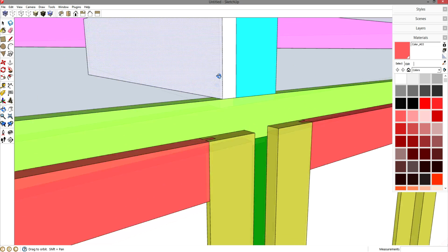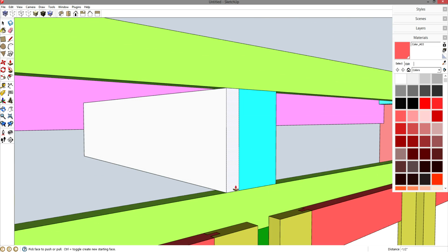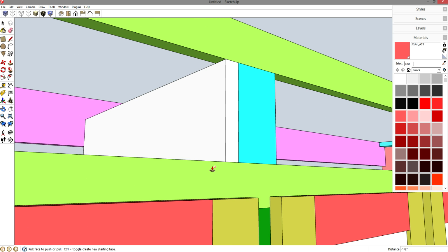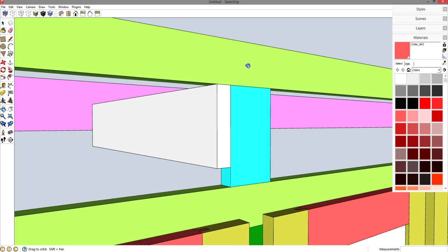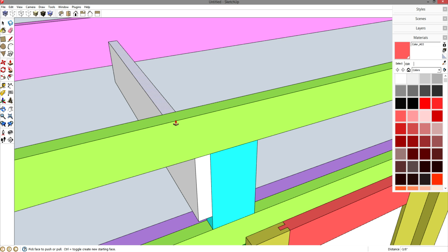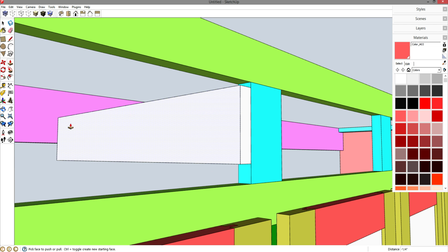Now, the drawer slide is about half of an inch off the base of here. So let's go 0.5, enter. And I also want to just put the bottom of the drawer right onto the bottom of the side. So let's push this again 0.375 because I'm going to use 3/8 of an inch plywood for the bottom of that. So that's my height that I have so far. And I also want some leeway up here. So let's just push it down again 0.25 inches. So that's pretty much the size of the drawer side that I need.